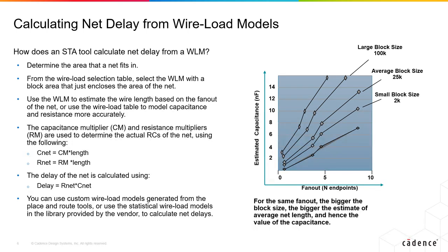To minimize pessimism or to simplify the net delay calculation, you can choose one of the multiple modes that the STA tools might allow, such as the top mode, the enclosed mode, and the segmented mode. Depending on the mode that is being used, varying block sizes are selected for the wire load model selection table. Therefore, to calculate net delay using the wire load models method, you need various wire load models based on various block